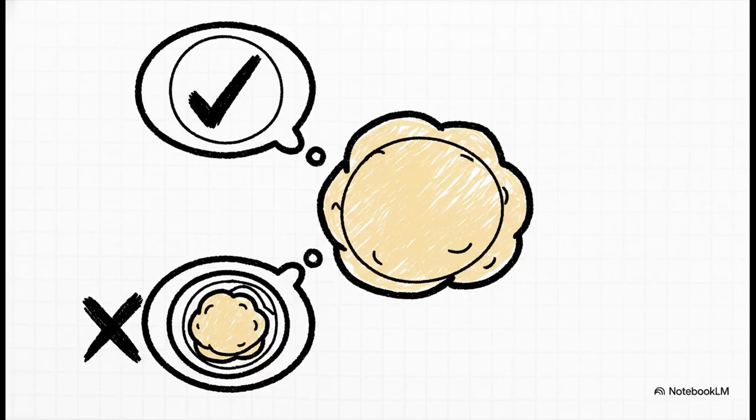And get this, even if you get the datums perfectly right, you still have to watch out for something truly wild called methods divergence. This happens when your CMM software offers you different mathematical algorithms to fit a shape to your data points. Let's say you're measuring a circle. Your software could use a least squares fit, or it could use a minimum zone fit. Both are completely mathematically valid, but if your physical part has an odd, sort of lobed shape from the machining process, these two methods can yield completely different center points and completely different diameter sizes. You could literally have a part pass inspection using one math algorithm and fail using another.